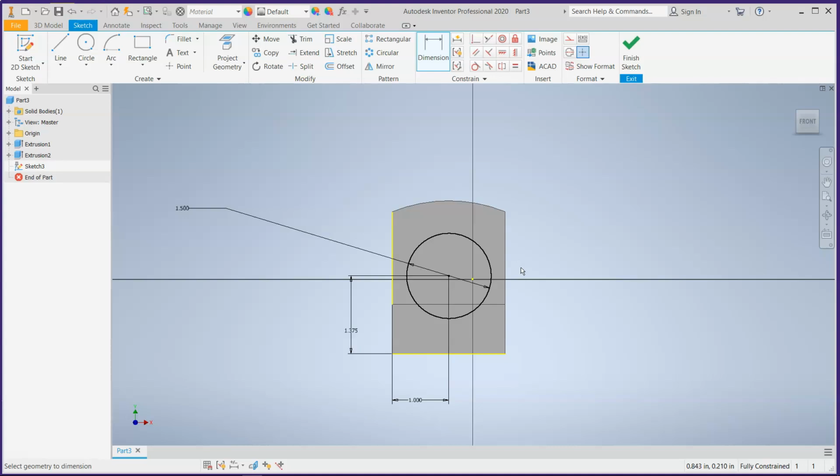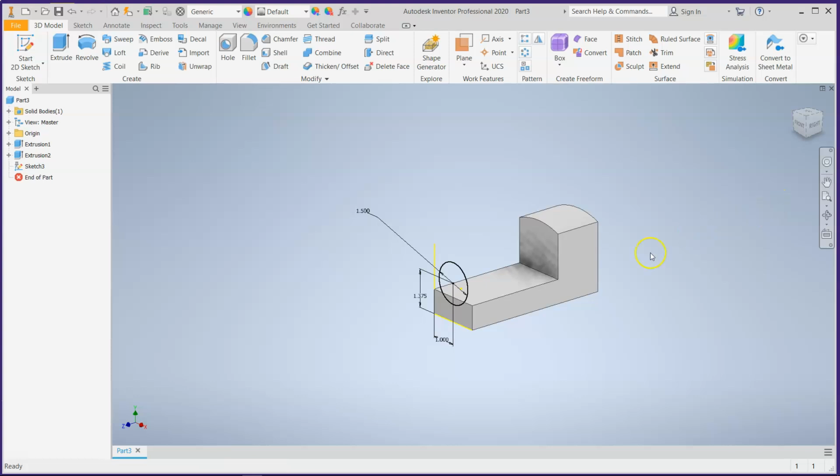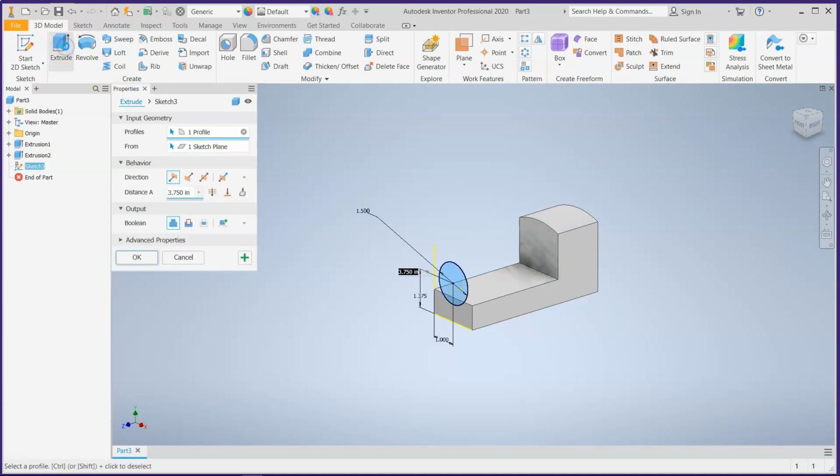This star symbol, which is Shift 8 on your keyboard, that means multiply. And now we have our circle, which we can then grow into a cylinder. So let's finish sketch. It's got our X and Y coordinates, and it's got our diameter. That's all we need. So we're going to finish the sketch, and now we're going to extrude material back here. So click extrude.